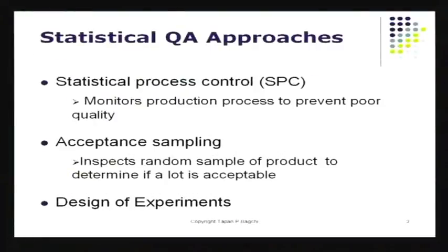So let's get into the lecture and let's try to understand what we mean by statistical process control, which is also called SPC. What is SPC? It actually monitors the production process online. As the widgets or as the output is coming out, you measure some certain characteristics of interest of the output. Then you collect some data, which would be a sample taken out of the output, and then you look at the statistic, which could be something like XBar or P or R or something like that, and you trace basically the variation of that statistic.